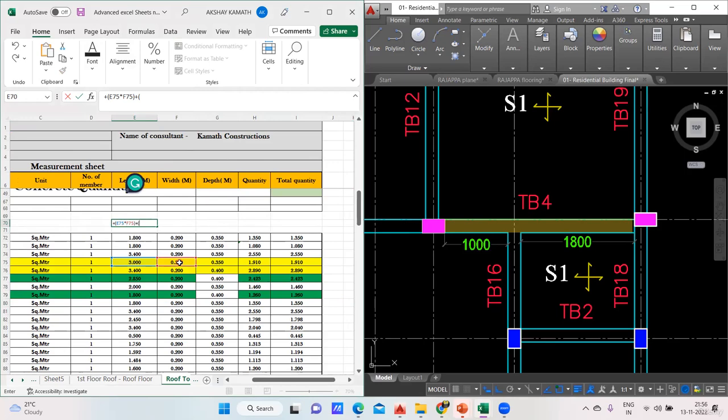Your bottom will be done. Now you think whether it's outside or inside. Now I'll calculate only this part. Why? Because I don't have a slab in this portion. So this becomes my outside shuttering, whereas this becomes my inside shuttering, because I have a S1 slab here.